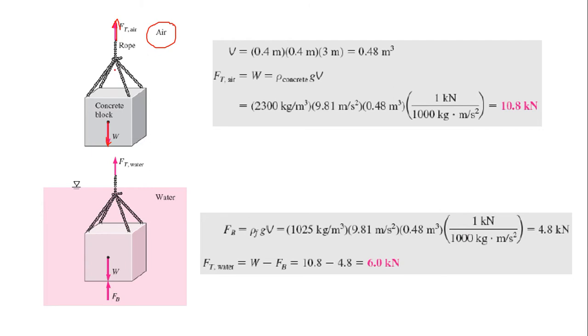So only those two, and because it's suspended in the air, there's no buoyant force. We are not in the fluid, it's just in the air, so the summation of forces vertical, and if you take this as positive, FR minus W equals 0. Very straightforward. So FR equals W, and your W you can find from rho GV. This is W, rho GV.